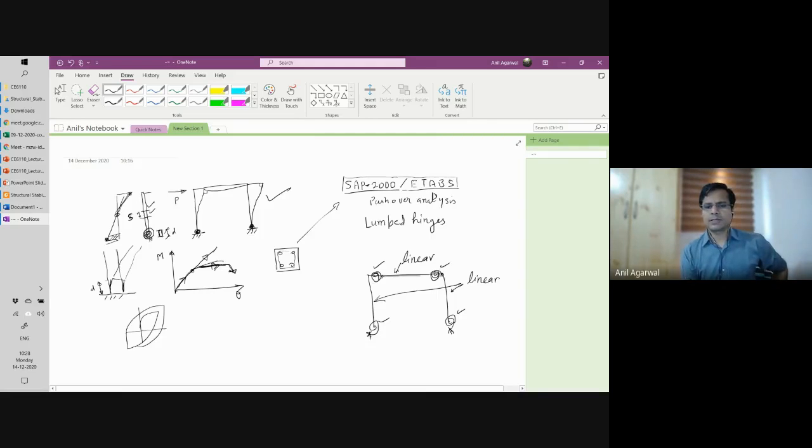So basically what happens in this case is you get one element, two, third, fourth, fifth, sixth, seventh element. So a problem which originally had three frame members now has been divided into a seven-member problem. Okay. You get me? So your stiffness matrix will now have seven members to assemble, and then all the degrees of freedom corresponding to those members. Got it?